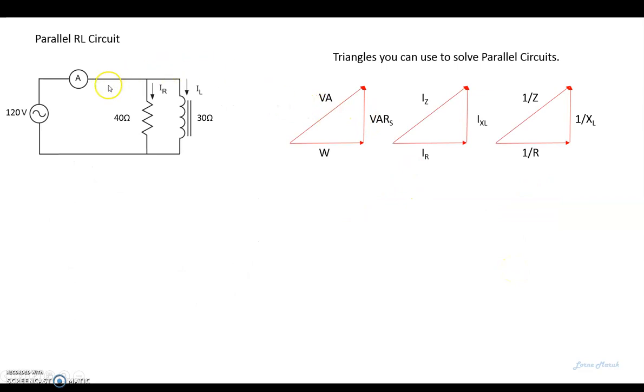So now we can try to solve this circuit here. And once again, we do have a resistance and a reactance. Don't get trapped into using the impedance triangle. It won't work. The impedance triangle will, but it is tricky. Draw your vectors to indicate that we are actually adding vectors together, straight up for the inductance in this case. And like I said, it doesn't matter which way you draw them, as long as if you're mixing them up, the capacitive reactance goes the opposite.